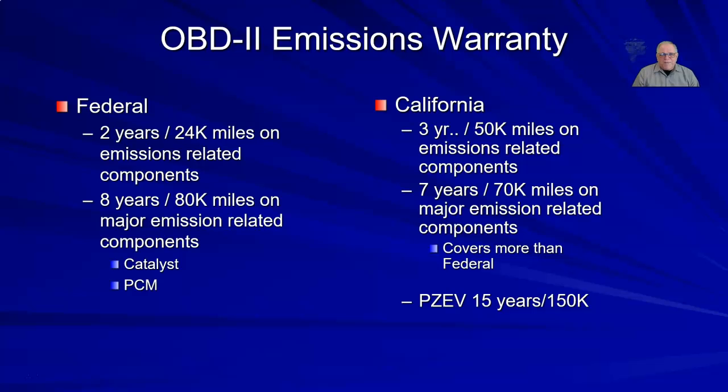If you've looked at the back of Subarus, they have a PZEV on there. That is not a model of Subaru. The partial zero emission vehicle is a California rating. What the PZEV means is that the vehicle has to meet the federal super ultra low emissions for that vehicle, and it can't have any leaks on the evap. So not even a 10 thousandths leak, it has to set a code. On a PZEV vehicle, it has to be warranted to be clean for 15 years, 150,000 miles.